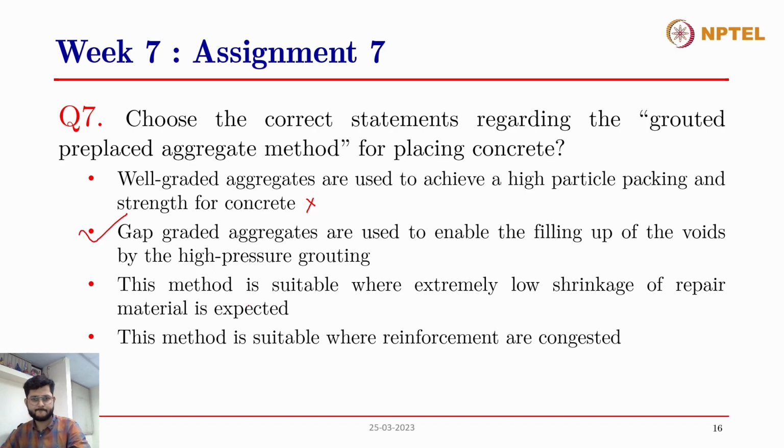And this method is suitable where extremely low shrinkage is expected. Yeah, the third option is also correct, because if the repair material has low shrinkage, then only we can apply this method. Otherwise, the grouted material will get loosened due to shrinkage.